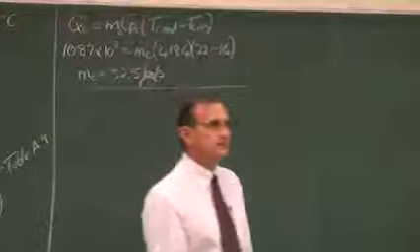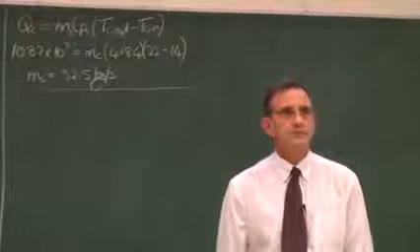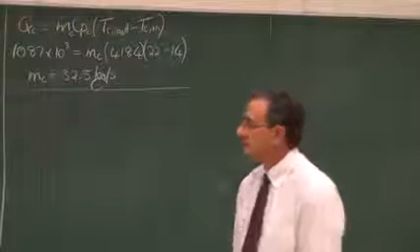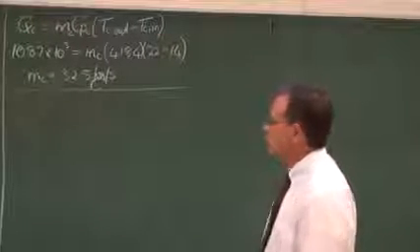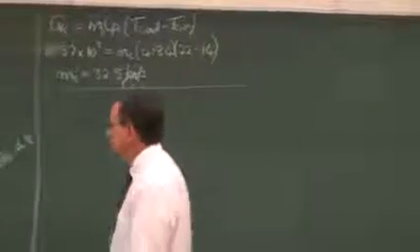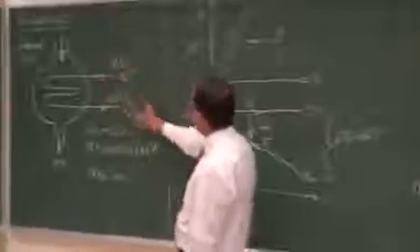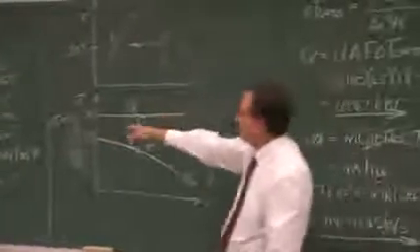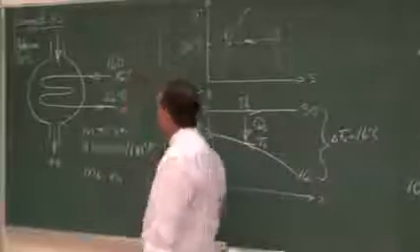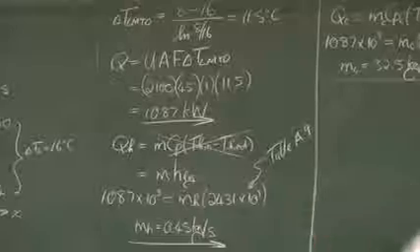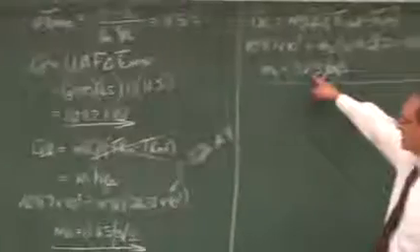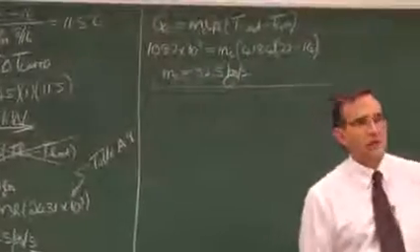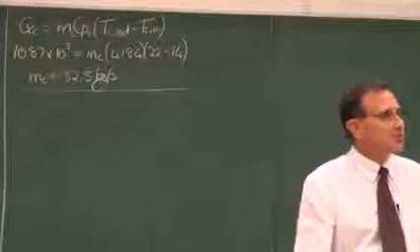Okay, any questions? Nothing? Okay, what this problem also shows us is how much energy is in steam. Just look at this problem. The temperatures of 30 and 14 and 22, both water. In the one case it is steam. To do the heat transfer rate of the steam, we only need about 0.45 kilograms per second, but on the water side, 32.5 kilograms per second. For the same heat transfer rate.